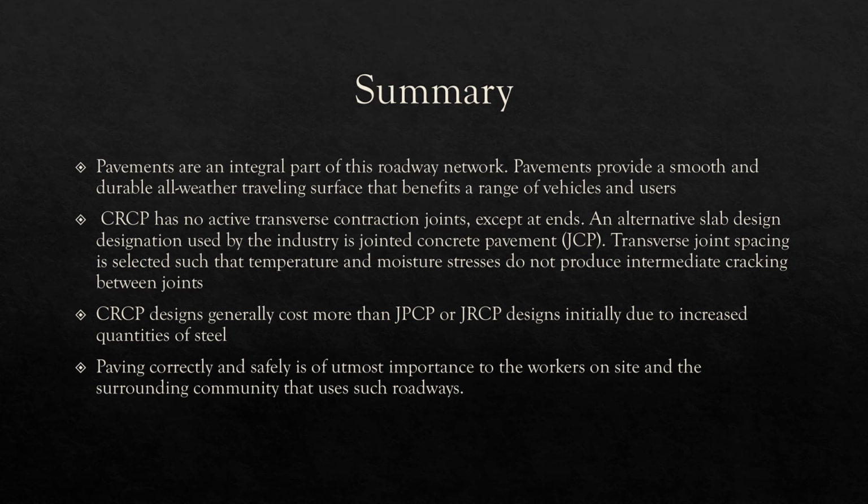Transverse joint spacing is selected such that temperature and moisture stresses do not produce intermediate cracking between joints. CRCP designs generally cost more than JPC or JRCP designs initially due to increased quantities of steel. Paving correctly and safely is of utmost importance to the workers on site and the surrounding community that uses such roadways.